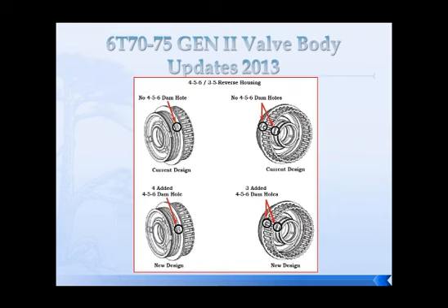If you turn that whole assembly around, you would see that we've got some holes drilled into it. And so by looking at the hole designs, they've added 4 holes on that 456 clutch drum on the left-hand side picture. They've added 3 more holes on the right-hand side picture. So again, you can physically look to see if those holes are there to tell you if you have a first design or second design 456 3.5 reverse housing.